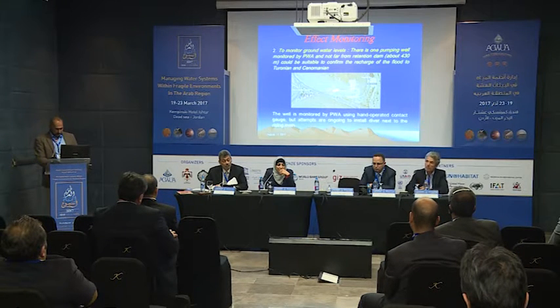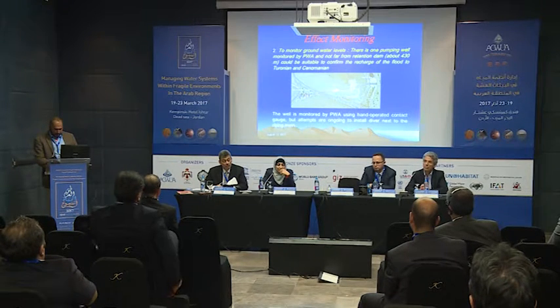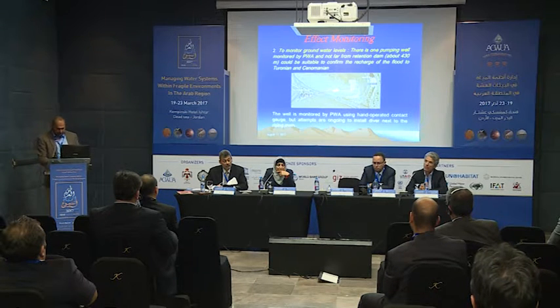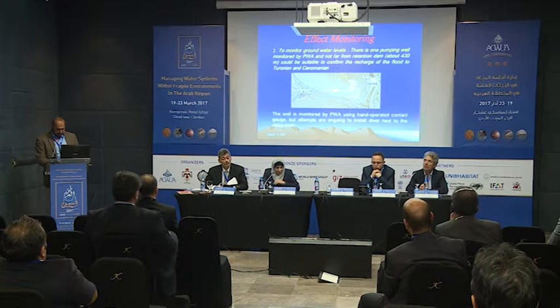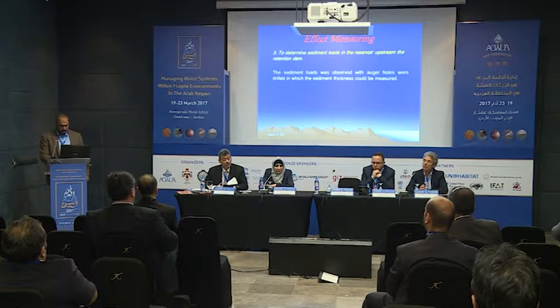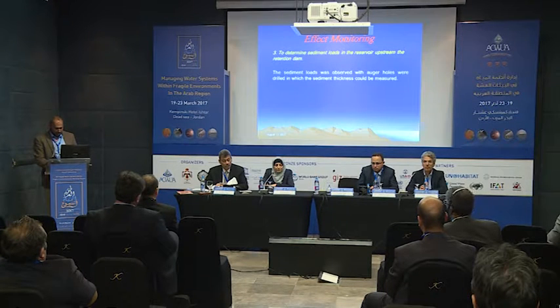And also we need to monitor groundwater level. We have one groundwater well. It is about 500 meters away, and this can be used to monitor the effects of the artificial recharge, but it needs a diver to be installed at the rising main to the well. Also, we have to determine the sediment load in the upstream reservoir to assess the artificial recharge, and sometimes we need to remove these sediments.